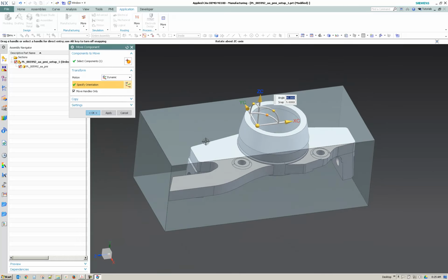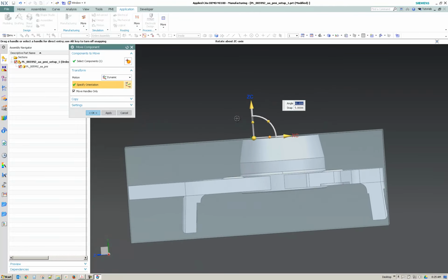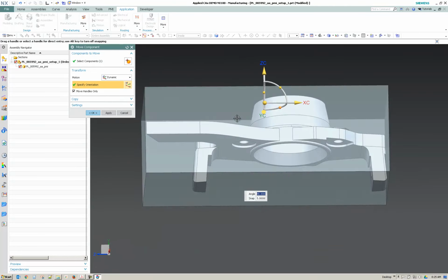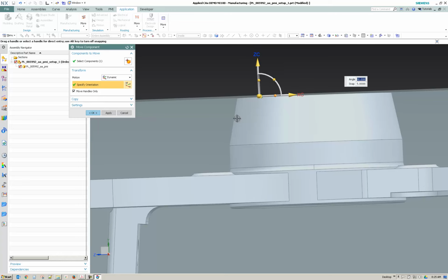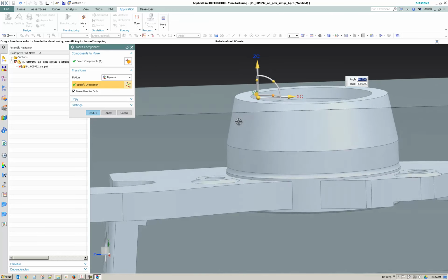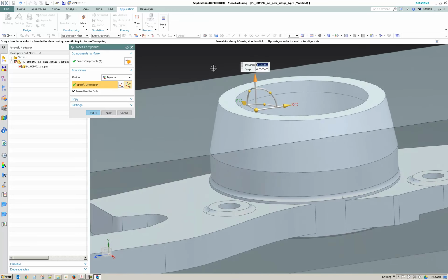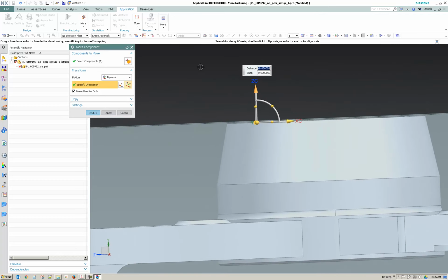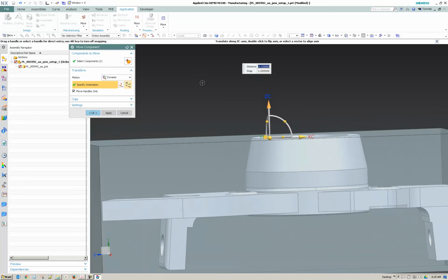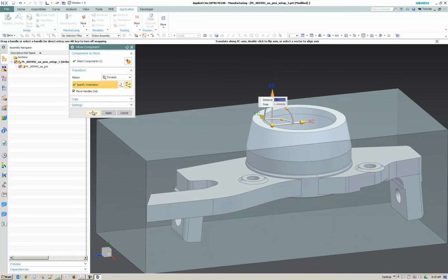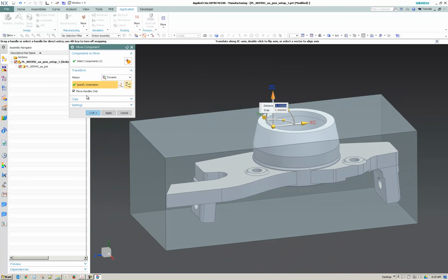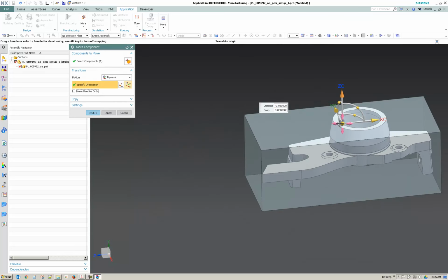And so now this looks like what I will want the part to look like when I'm set up. Now we do have the stock value on the top, so we had set it to 30. We can go ahead and lower the Z by selecting the cone and entering minus 0.030 thou, and this will set it to the top face of the part. And I'm going to say OK, uncheck the radio dialog for the move handles only, and now we can move